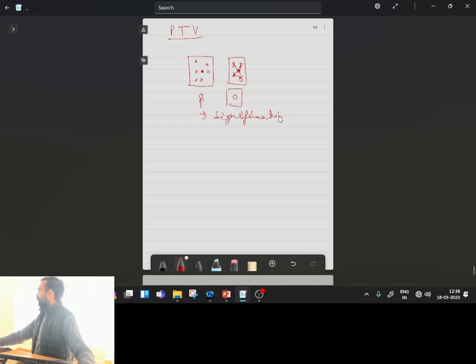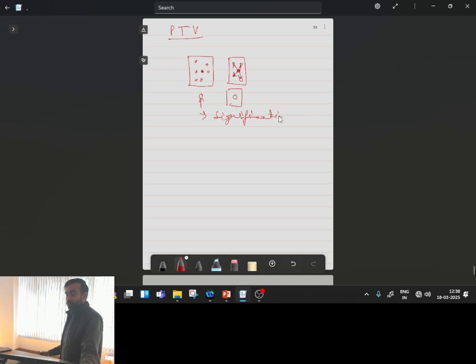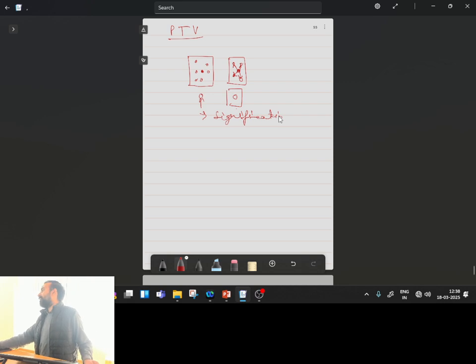That type of PIV measurement is called particle tracking velocimetry, but its use is still limited. Only very advanced systems with advanced cameras are able to do this, and that too for very small visualization windows, like in microfluidic devices. For large scale, this type of measurement is still a challenge. But one advantage is that, in comparison to the subframe based correlation, the individual particle based correlation gives you better spatial resolution.